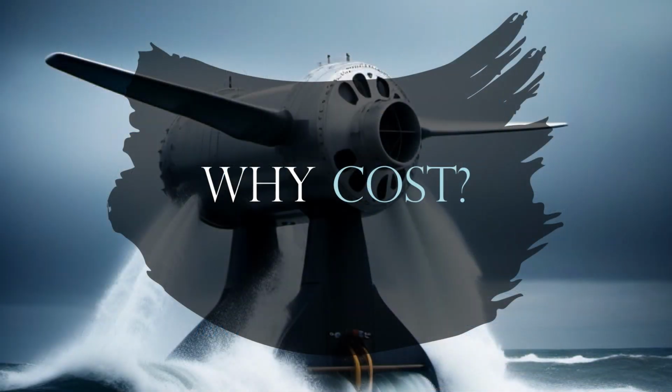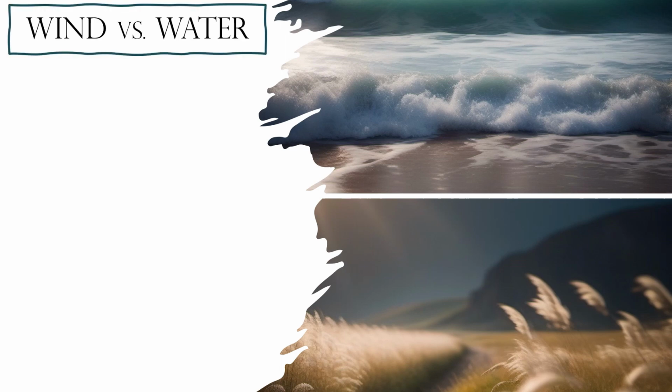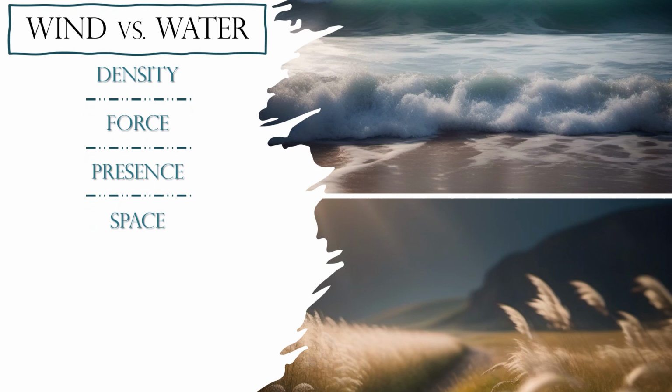So, why cost? Well, let's take into consideration the comparison of wind versus water in terms of density, force, presence, and space. As you can see in the bottom left figure, water is far denser than air, with air having a density of around 1.3 kilograms per meter cubed, and water having a density of roughly 1,000 kilograms per meter cubed. Doing the math, this makes water around 800 times denser than air.